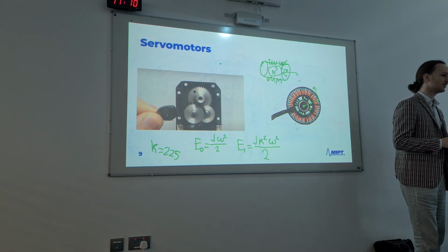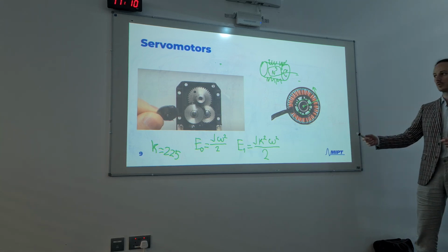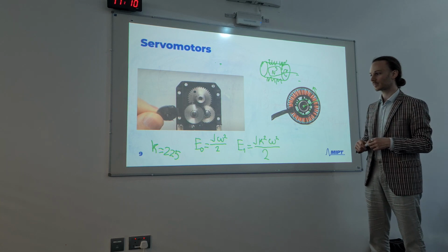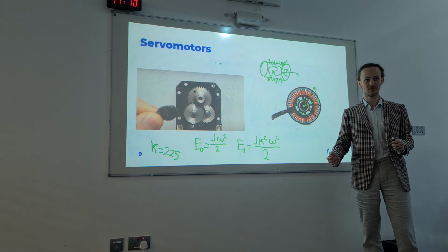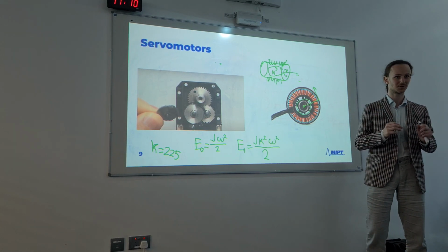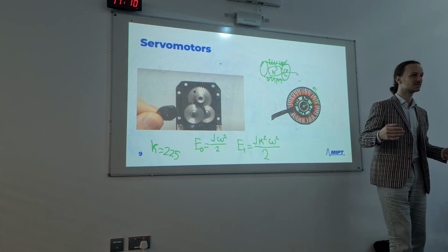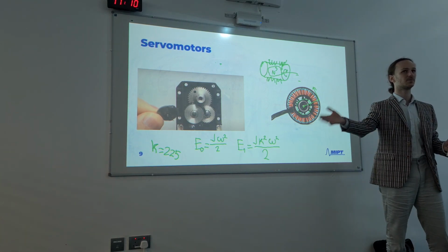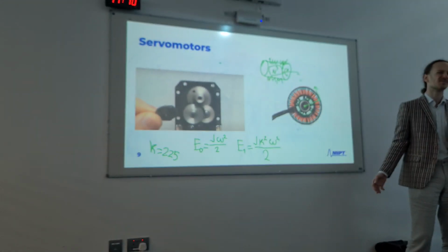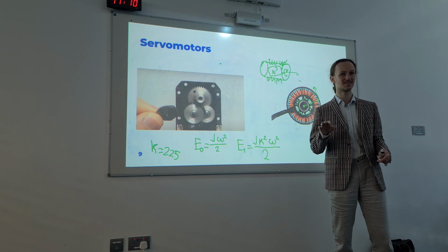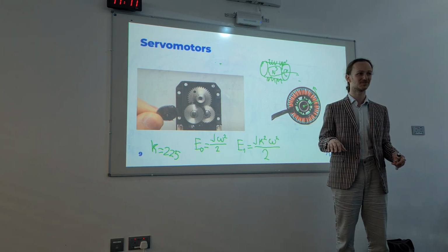And it is enough for these motors to have a gearbox of 1 to 6, 1 to 9, 1 to 10, something like this. And they become backdrivable, which is awesome. So imagine something goes wrong. Robots fall over, and what do you need to do? Well, one of the best things to do is just to switch the power off and wait until everything stabilizes.